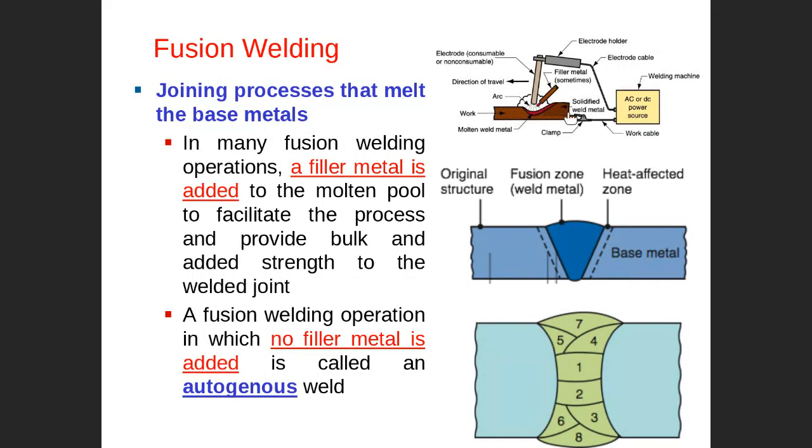This filler must be compatible, actually. This filler material that we use, when we heat, the filler will melt and deposit in the welding zone, and it is compatible with the base material. The functionality of this is to compensate for the material evaporated during the welding process and also to provide bulk to the weld and so on. So this is a weld done here in fusion welding.